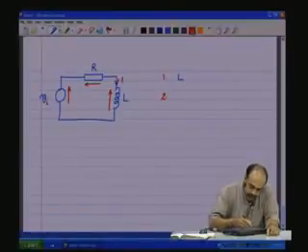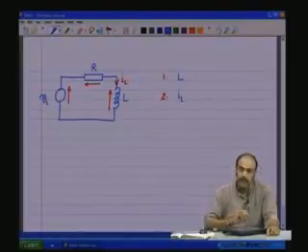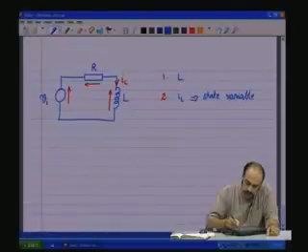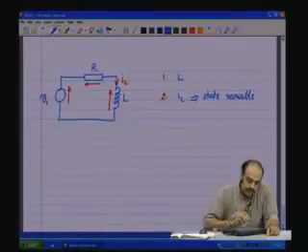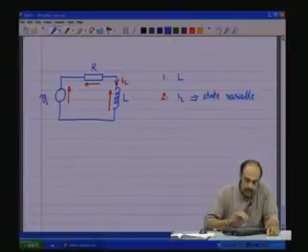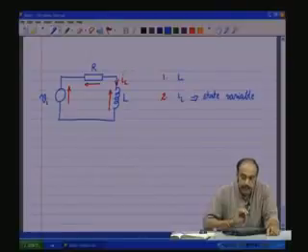Therefore IL is the state variable. This is the state variable. And in the circuit, you just have those variables only that are essential for making the equation, which is the input variable Vi, the state variable IL, and the parameters of the circuit R and L. You need not mention any other variable other than this. These variables are sufficient to completely describe the circuit.